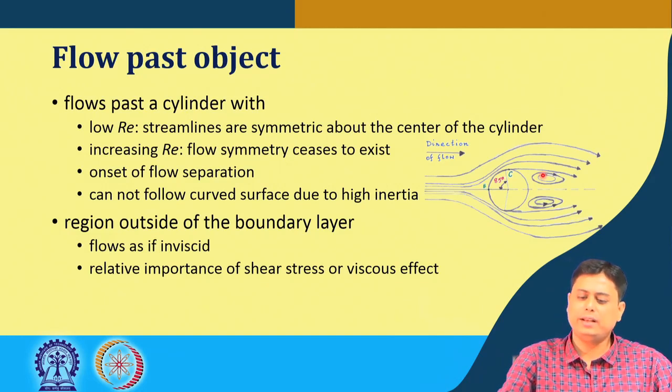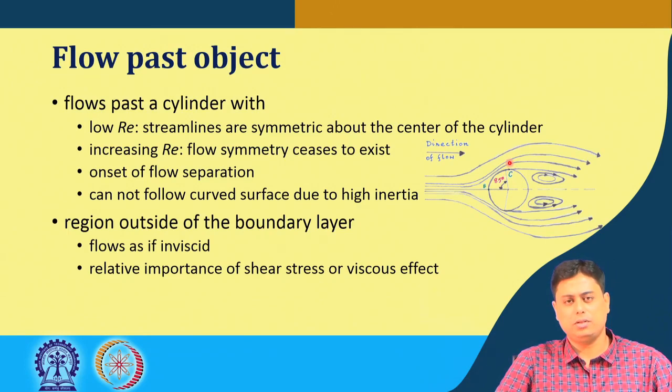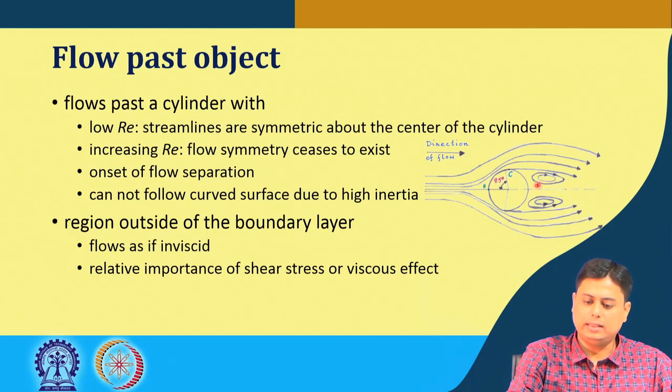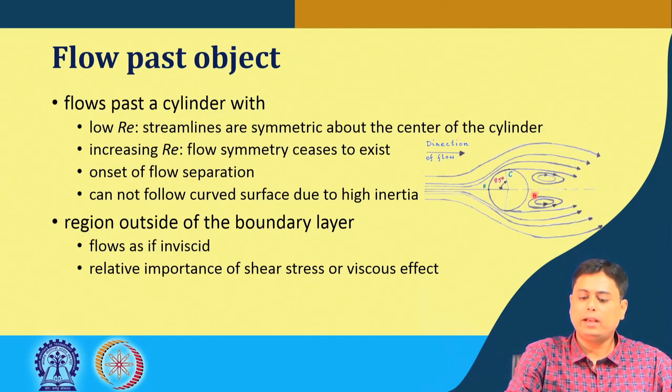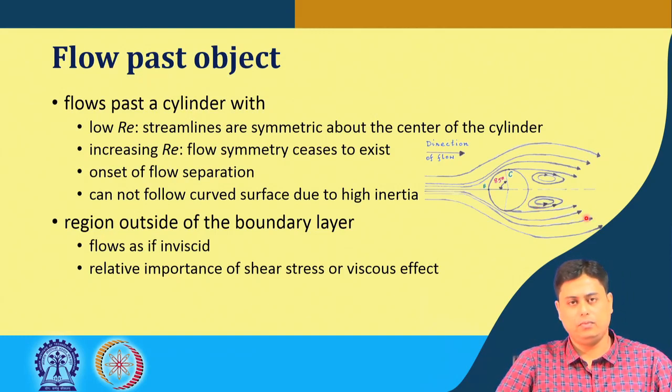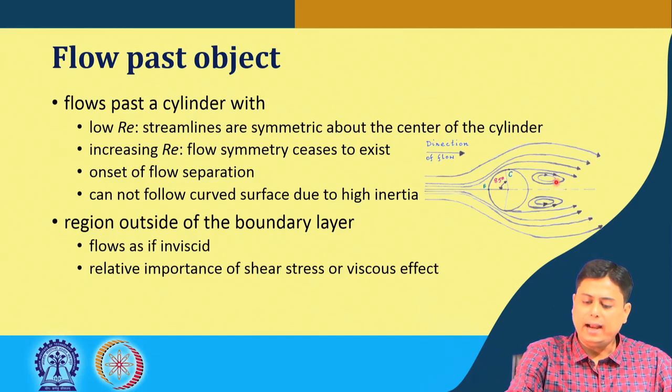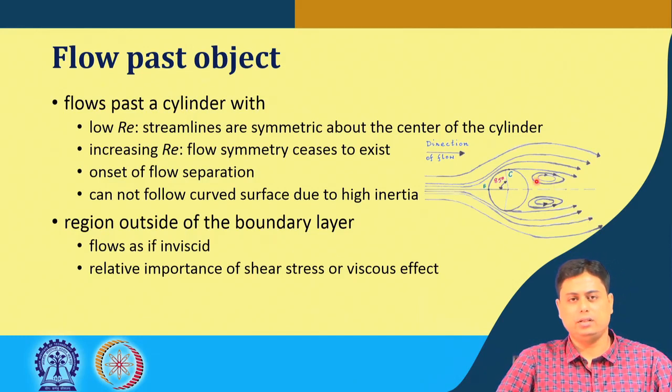As it goes higher and higher, there is the onset of this separation point, and as it happens exactly at the rear point of this object, a wake formation happens. There are wakes that form, and in fact, here the flow in this region is opposite to the direction of the upstream flow, and that creates a huge pressure gradient.